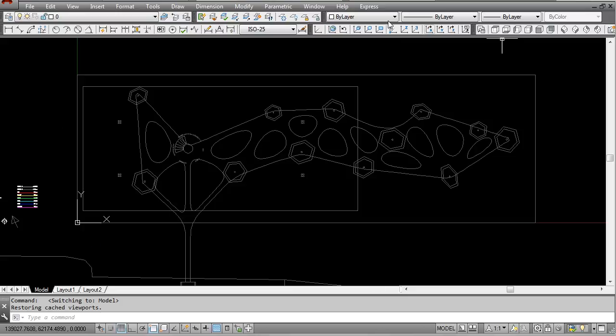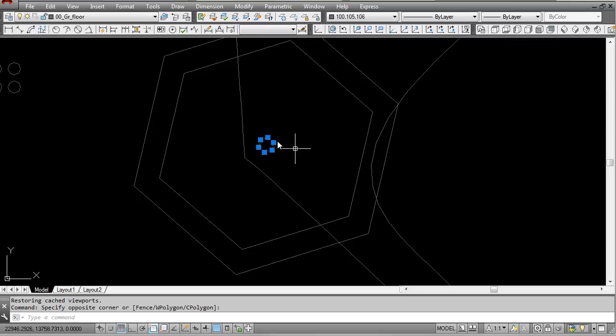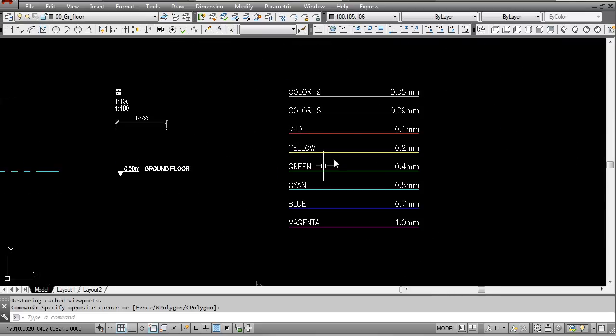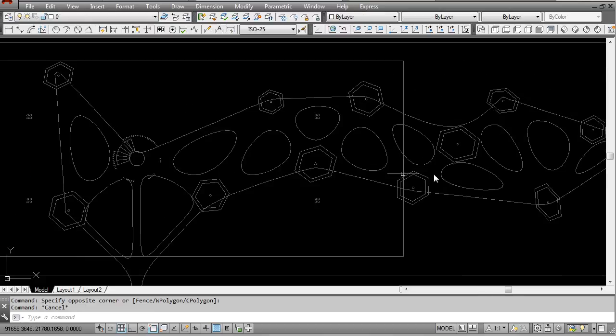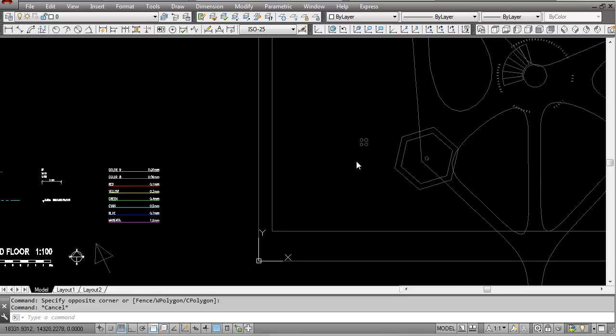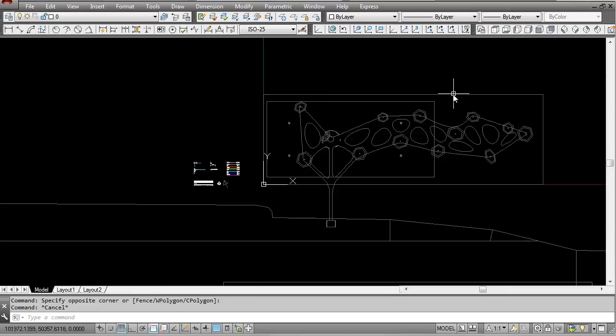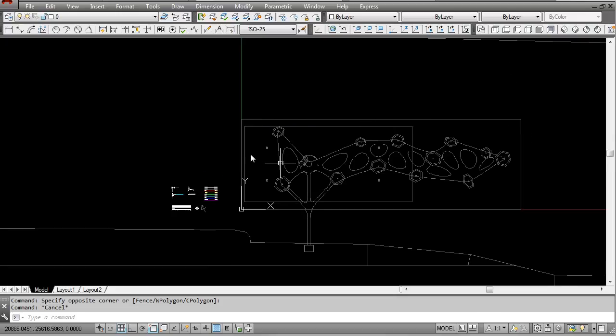So for our plan and for our purposes, we're busy doing a design plan. So we're going to be using these color thicknesses to correctly represent how things are being viewed. Now generally we use the thicker colors when things are being cut through. In our case we have some structure like these columns being cut through, so we could use a color like yellow for that. We have certain floor elements that are going to be seen quite close to the view, so we could color those in red, and then the elements that are going to be further away or less visible or less pronounced are going to be colored in gray. So let's go ahead and set that up.